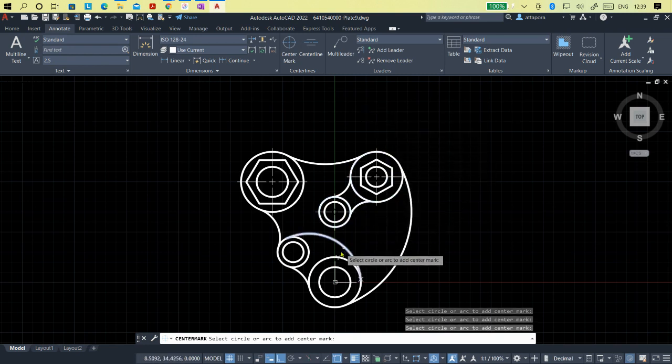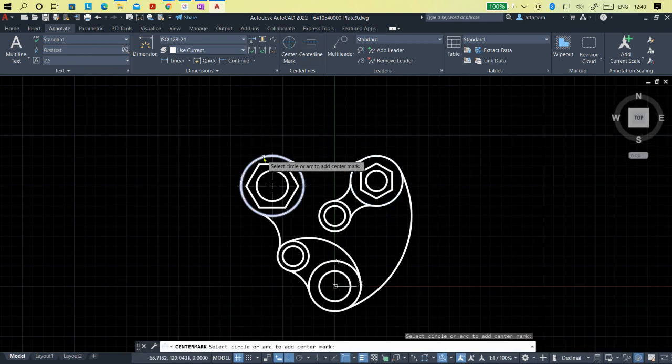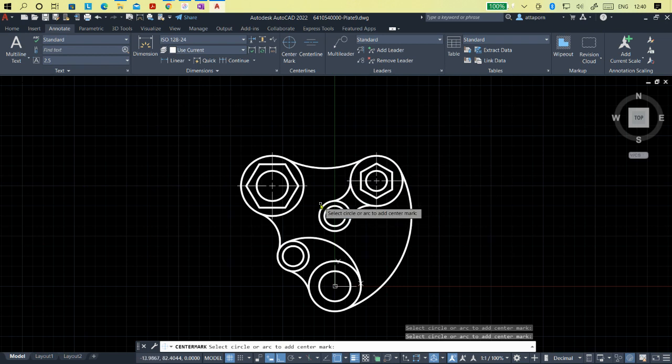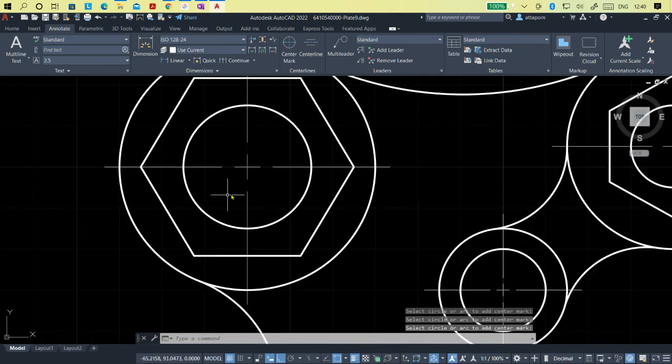Okay, really easy for center line. Maybe finish. How about if we click here? It is a center point that we don't use, because this curve is made from tangent and tangent, not from the center point. So maybe I have to click it again so you can see it again. Okay, and enter. So you see that is the center line.